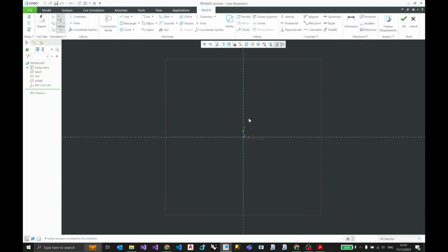window. Now, over here, where the horizontal and vertical axes match, is the origin. And we're gonna reference our drawing from this point. So now we have entered the sketcher mode. I don't really need to see this plane, so I can go over here and uncheck the plane display option so that we've got more room in our sketching window.